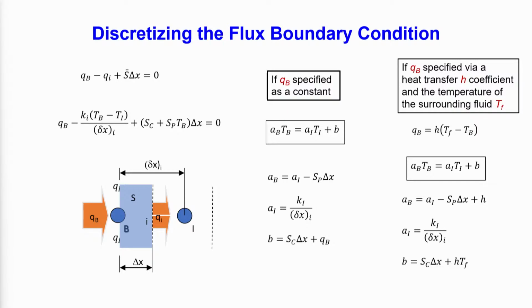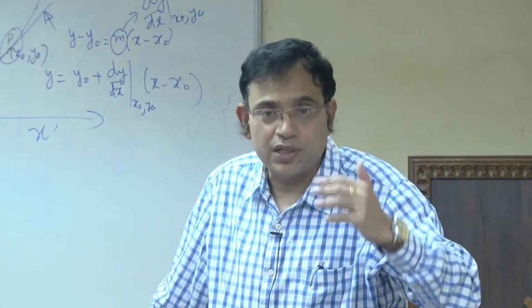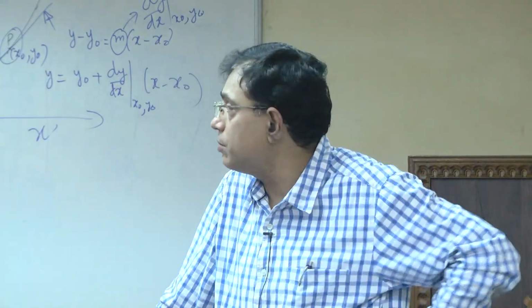At one of the boundaries heat flux is given, so that is a given number qb, and the others you can write. Now you see an interesting thing: temperature at the boundary is given in terms of the next point I, but there is nothing to the left of the boundary. Although it is a two-way coordinate with the elliptic problem, at the boundary it becomes one way, and that is how you can start propagating the solution from the boundary, and that is physically implementing the boundary condition.